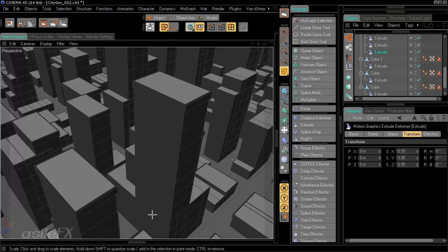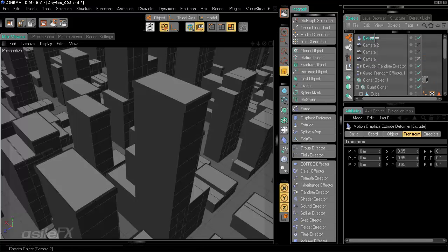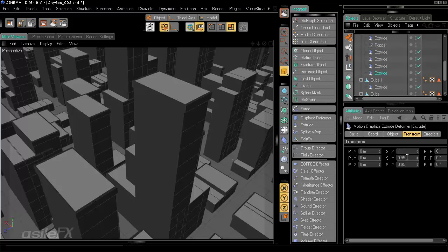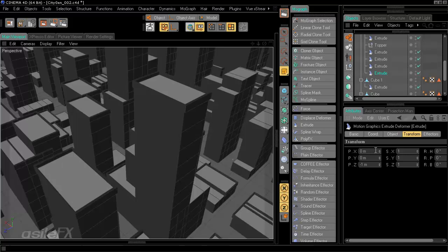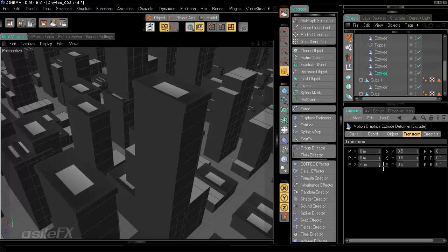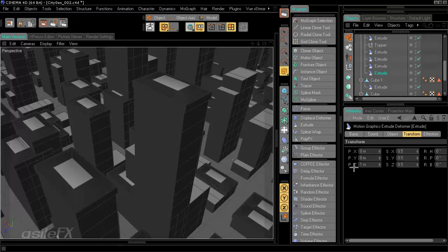And then if we want to sink it in, we need to have one more. So we can copy and paste the extrusion again, add it to the list, and then keeping our scale the same, set it to a -1. We could sink it in quite a bit. If you did want to scale it down, we could shrink it quite a bit if we wanted to really pick up a highlight, maybe have it uneven, or we can make it go in the other direction. Instead of going negative, we can raise it and get different building toppers that way.